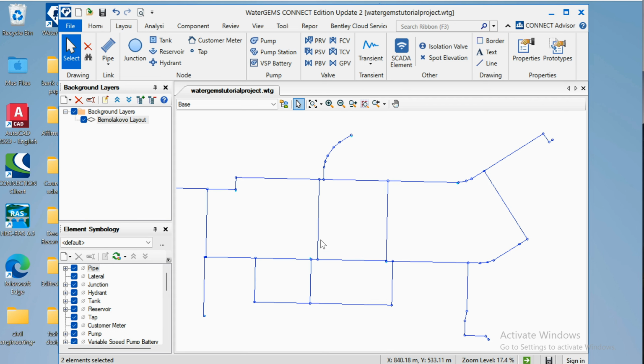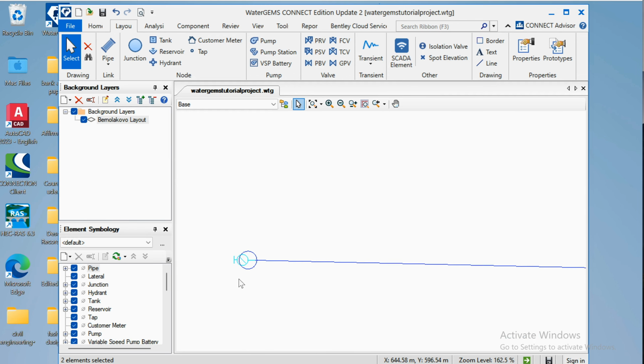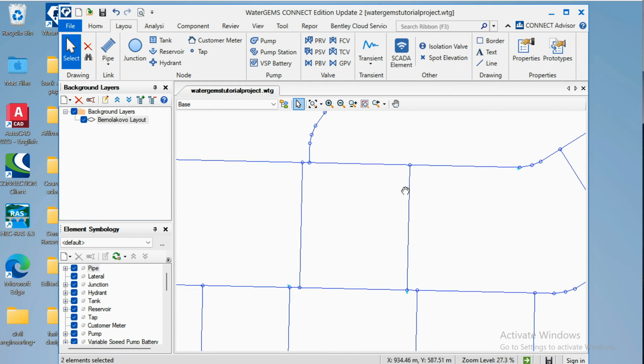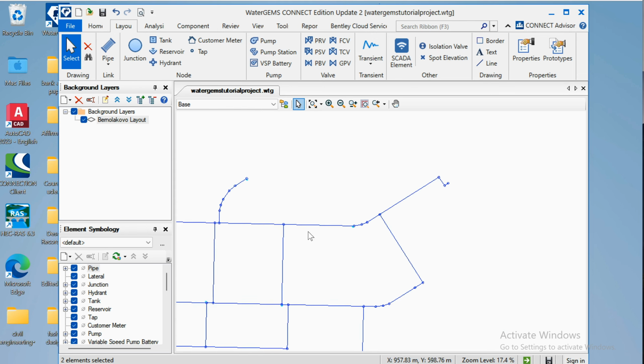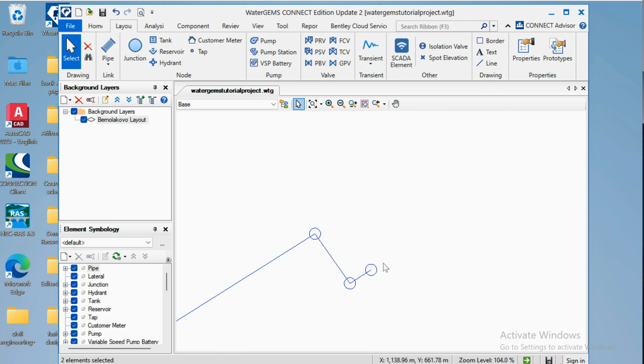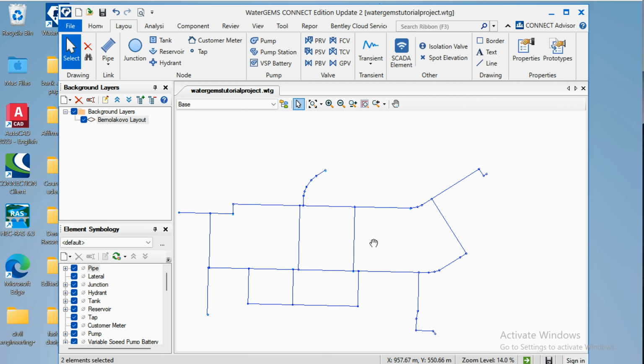And all right, now to start drawing, you need to know where you would like to start. So usually what I did was I wanted to start off in the same order of my junctions, because I already have them numbered in Excel, and in my AutoCAD file they were already numbered. So I would start in the same order. In my own opinion it would be better to stick to the same order, because later on you would need to add the characteristics of each junction and the characteristics of each pipeline. Also, you need to write down the elevation. So whenever you do it in the same order of the junctions and the pipes, it is the best case.